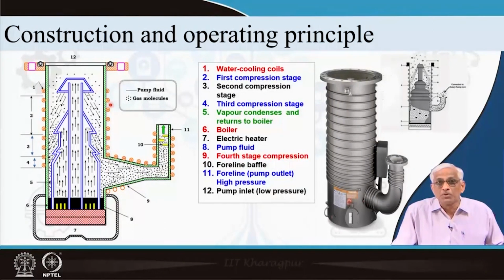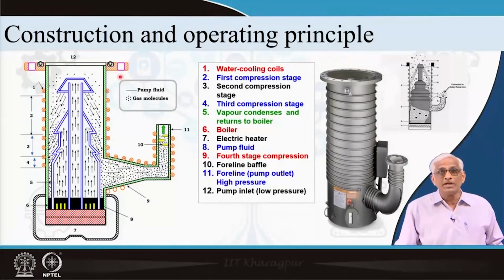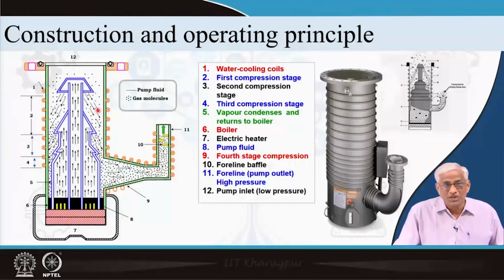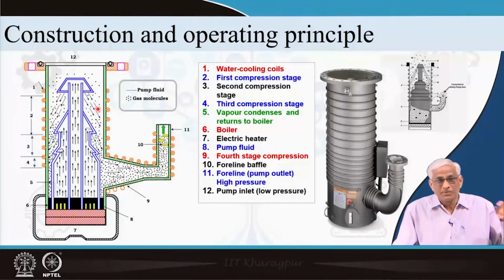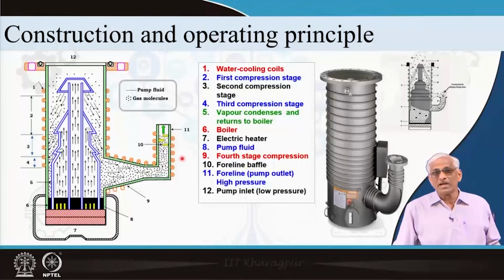This type of fountain principle creates a supersonic jet of high molecular weight oil molecules. They will hit the otherwise free molecules, which are moving around at 10 power minus 2 torr, originally created by the rotary pump. They will be baffled down, because only molecules can compress molecules; no piston or mechanical thing can compress here. So it is not like a compression-expansion principle; they are basically baffled down. The molecular momentum transfer is going on there and this way they get compressed.